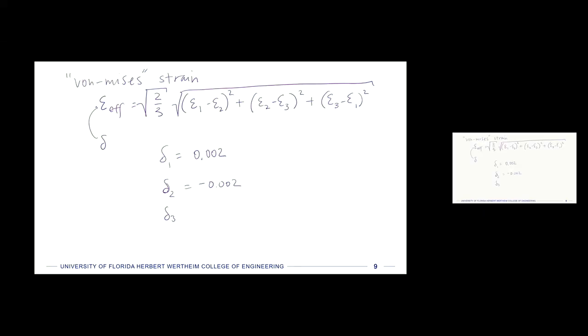Okay, good questions. All right, the last problem I have prepared is, I think it's 1311. I don't think I wrote down the problem number here. But it talks about the cumulative strain theories, and it gives us a chart, and then asks us to use the 3 different theories. So they had the time hardening rule, strain hardening rule, and then the life hardening rule.